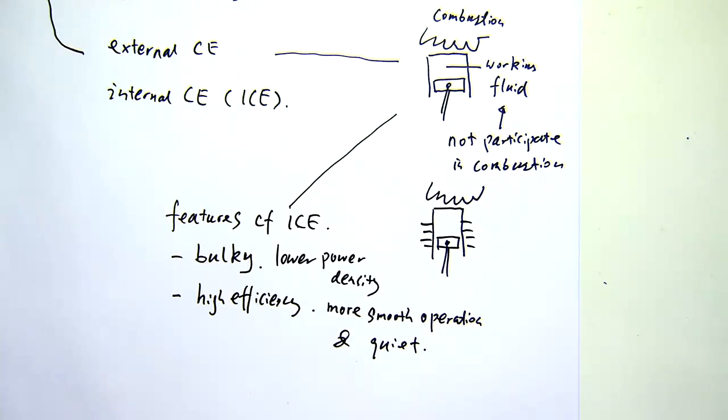So this type of submarine uses the so-called Stirling engine, which is the same cycle driving the small car we just saw a minute ago. They are using the feature that the engine is very quiet, and that's the key design requirement for a submarine, right? Because you don't want to produce a lot of acoustic signature to attract your enemy. So that's one of the places where the external combustion engine still finds a pretty good application.